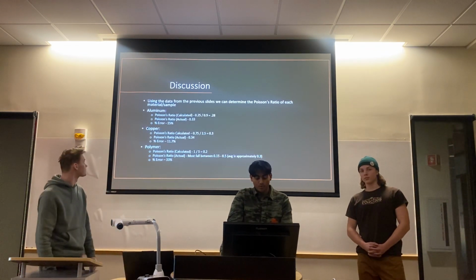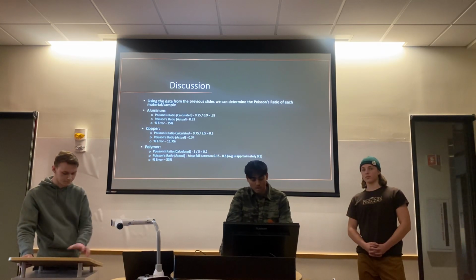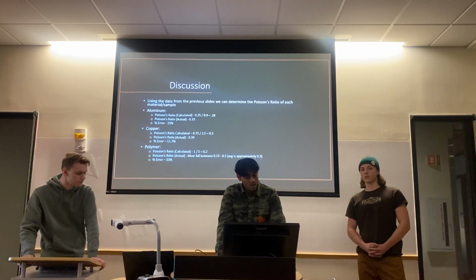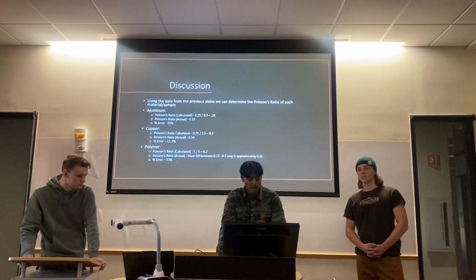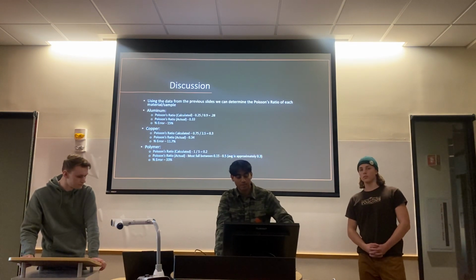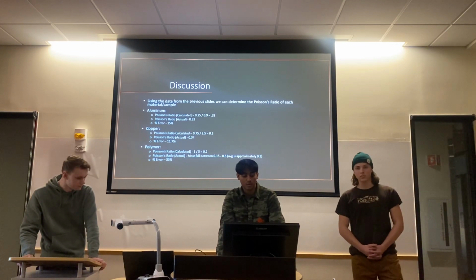So from this data, we calculated the Poisson's ratio for each sample. For aluminum, we have a calculated Poisson's ratio of 0.28, which is about 15% off from the textbook counterpart of 0.33.